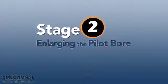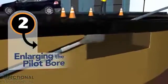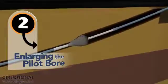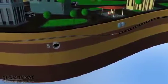A typical mid-sized directional drill uses a 4-inch drill bit to drill the pilot bore. The bore path is typically enlarged to 1.5 times the size of the conduit that is being installed. In this installation, the bore path has to be enlarged to accommodate the conduit, and a reamer is attached to cut a larger diameter hole. The reamer is simply pulled through the existing bore path to enlarge the hole.